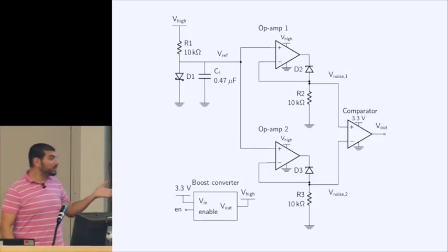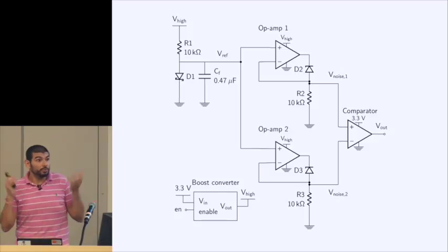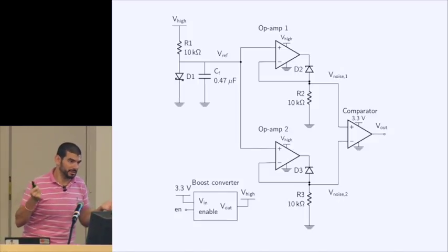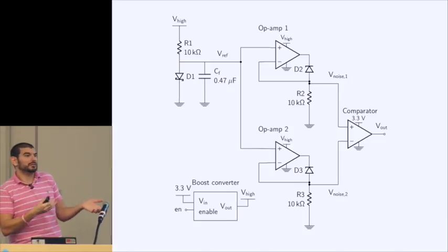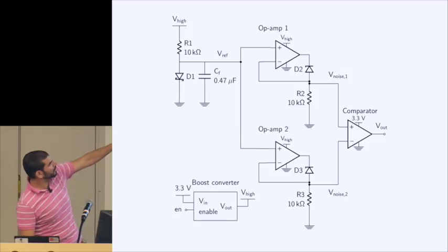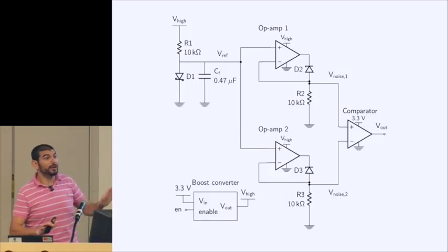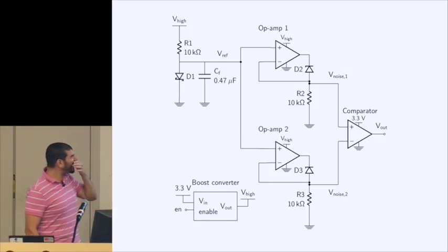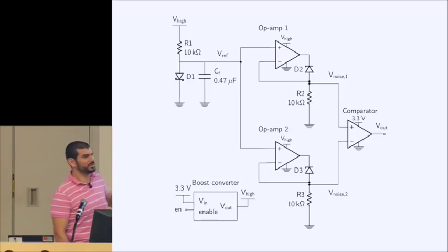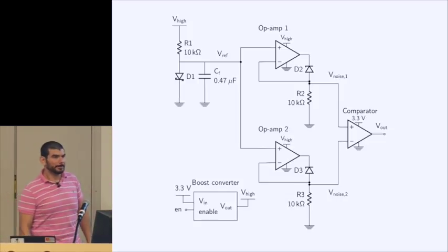So generally speaking, for practical reasons, you want to match resistors and not say capacitors or op-amp gains or something crazy, right? Because at least resistors we can test and they're relatively stable over time and temperature. So yeah, I think there's no doubt that what I've called R2 and R3 here absolutely need to be matched. But I think I'm not so concerned about whether op-amp 1 is exactly the same as op-amp 2. Yeah, okay, and the second question.